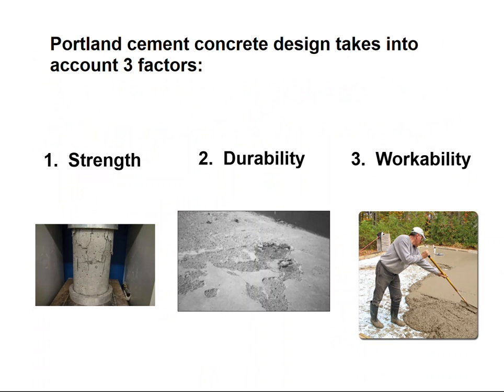And then workability. Workability is the only property we care about that's not attributed to the final product, right? So how easy is it going to be to work this concrete into whatever form or mold we need it to fit into? We can add certain things like plasticizers or admixtures to make it more workable, but as you'll see here in a couple slides, increasing workability can have a tendency to decrease the other two properties, strength and durability.